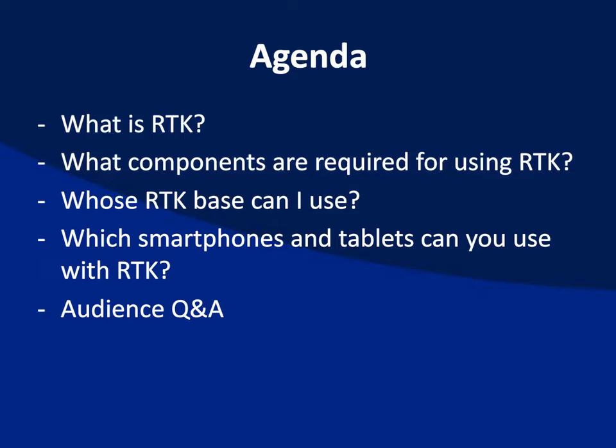These days, there are so many RTK bases out there that are publicly available, some subscription-based, some fee-based, but nevertheless, there are lots of RTK bases out there that you can tie into, so you don't have to deal with that part of it. You can just pull up to your job site, pull out your rover, and start it up and get your internet connection going, and you're golden. All of a sudden you're at 1 to 2 centimeter accuracy within just a few minutes, and so it makes it a lot easier than it used to be.